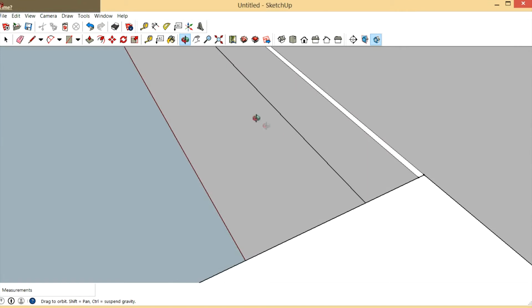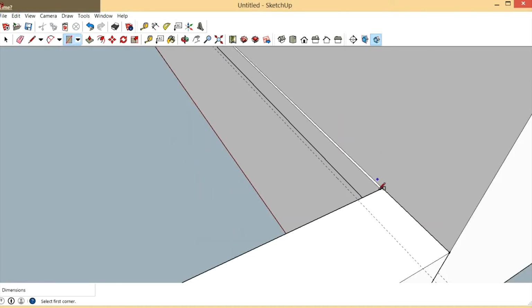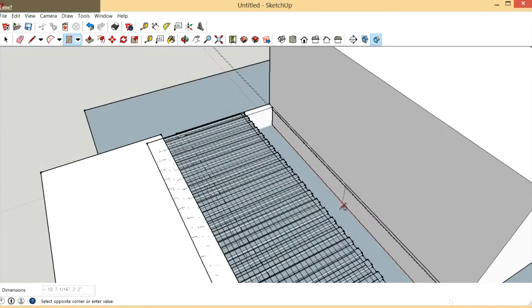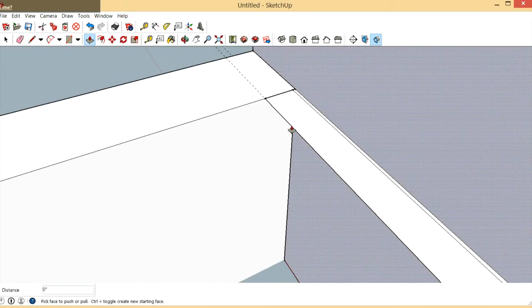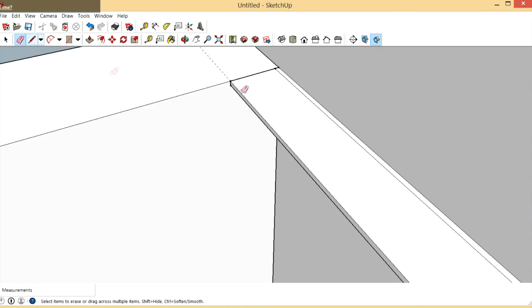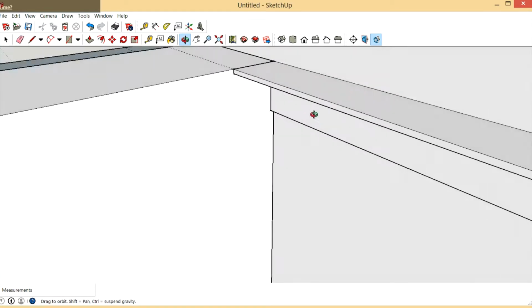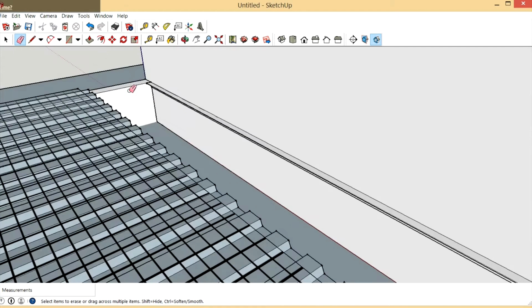It would also be 3 inches. It would be an L shape, right? So it would stick out 3 inches this way. Let's take our rectangle tool for this one, and we'll snap to this corner. Then we'll zoom out, and we'll go all the way to this corner, and we'll put it there. And so then it would be a 1/4 inch thick. So I'm going to take it down, and again I'm just going to drag it whatever length, then type in 1/4. Then I'm going to get rid of this little line right here that I don't need anymore. And you can see we just created ourselves an angle shelf there that would be bolted to the house.